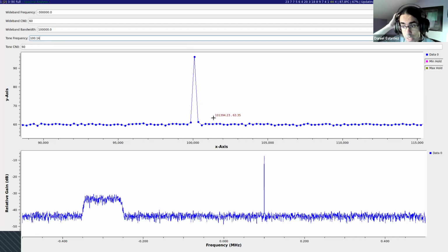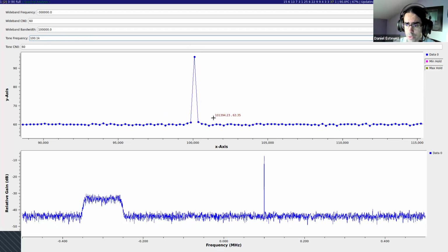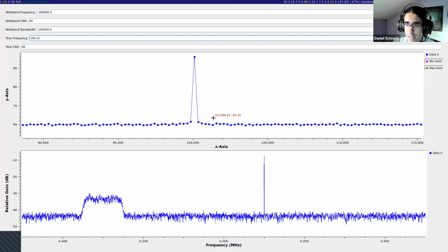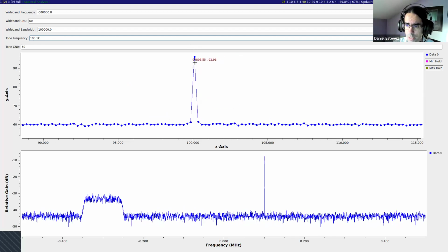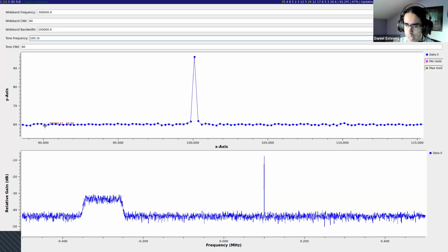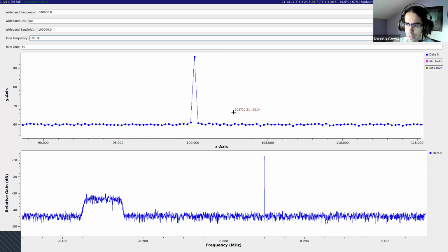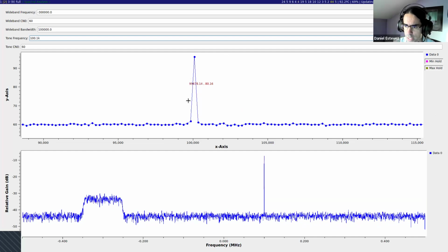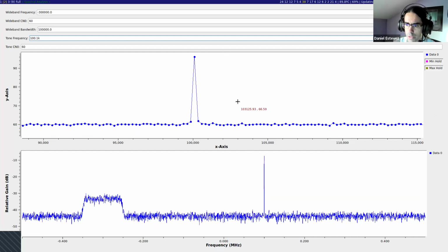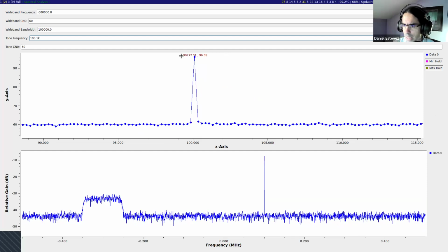And that's because of how the FFT works. With no window, if you throw in exactly the frequency of one of the FFT bins, you only get something in that particular bin and zeros in the rest. Here I'm getting the noise because I have some noise floor, but mathematically with just the input signal, I would get zeros everywhere else. So that's the nice thing about the rectangular window.